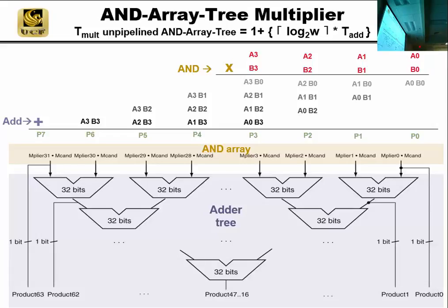So what's interesting is, if I multiply 2 bits, there are only 2 choices. 1 times 0 is 0. 1 times 1 is 1. Also 0 times 0 is 0. So anytime I have a 0, I get a 0 result. The only time I have a 1 result is 1 times 1. What does the truth table look like? If this is A and B, it is an AND gate.